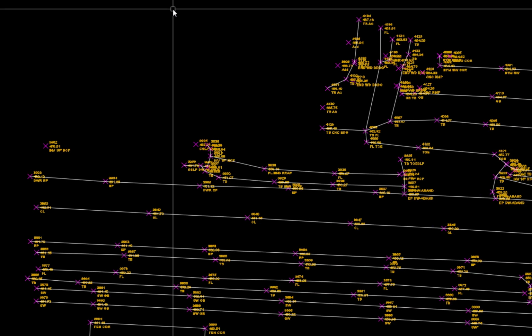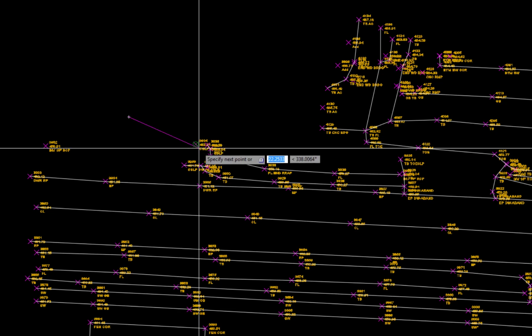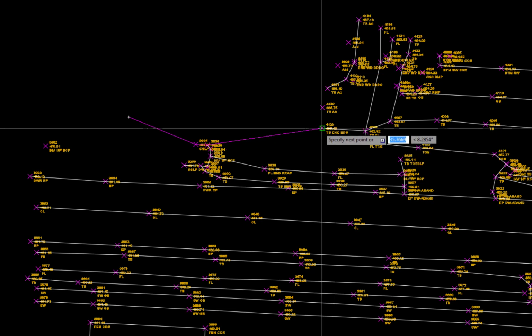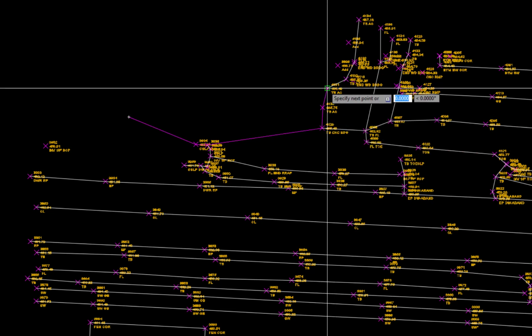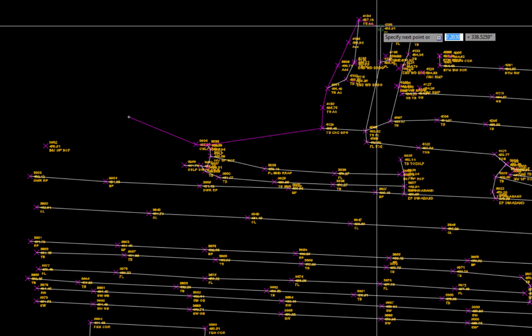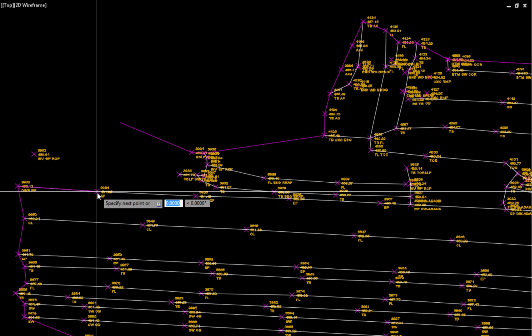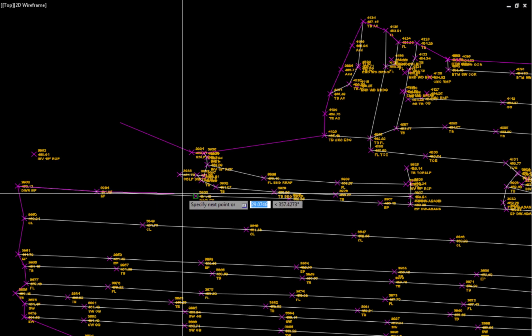Draw TIN boundary. Use polyline command PL, enter. Pick a clear area to start the polyline at elevation 0. Toggle F3 to turn object snap on. Pick point to point along the exterior boundary of the survey. Pick the last point in the boundary.